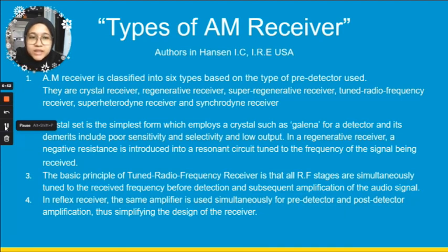In a regenerative receiver, a negative resistance is introduced into a resonant circuit tuned to the frequency of the signal being received. The basic principle of the tuned radio frequency receiver is that all RF stages are simultaneously tuned to receive the frequency before detection and subsequent amplification of the radio signal.